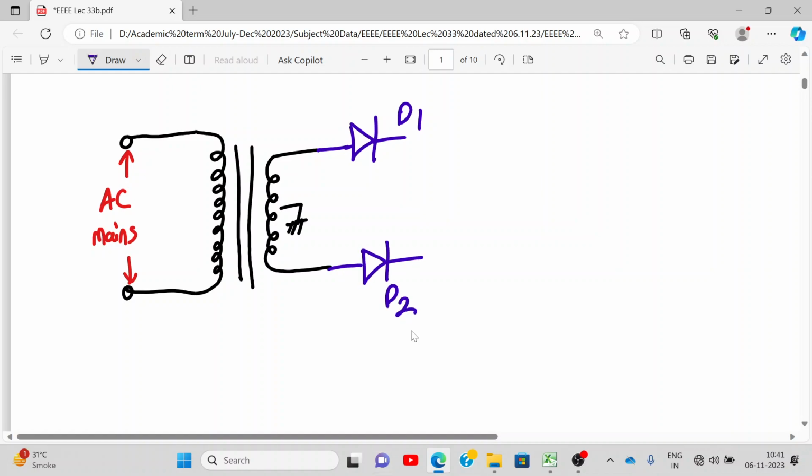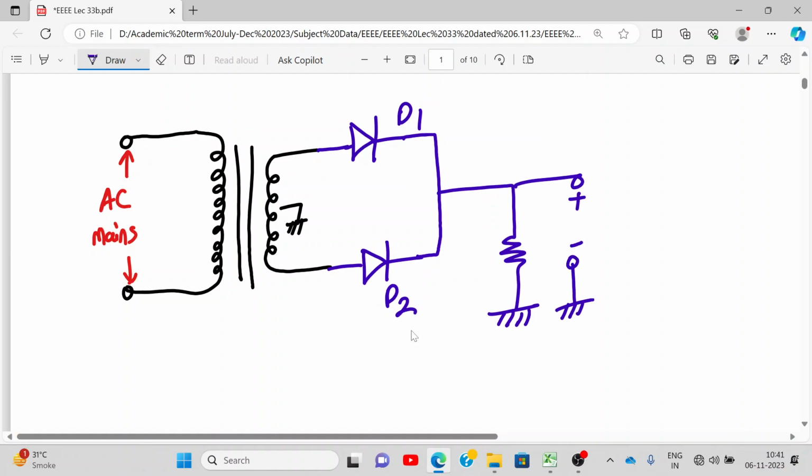Now remember, for all the rectifier circuits, we have to consider resistive load. So here, we connect them together, and then we connect it to resistive load. This is my Vout. So this is RL. Now, one crucial thing is, please remember this ground, this yellow color ground, this ground, and this ground are same. 1, 2, 3, they are same. Some books show you that they are connected between this and this. That will create confusion. Instead, I've drawn it separately.